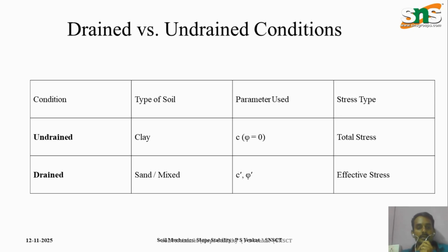Drained versus undrained conditions. It is essential to distinguish drained and undrained conditions. In undrained cases, like rapid loading on clays, pore pressure doesn't have time to dissipate. We use total stress analysis. In the case of long-term stability of sand slopes or slopes under steady seepage, we use effective stress analysis. Understanding this distinction prevents errors in design.